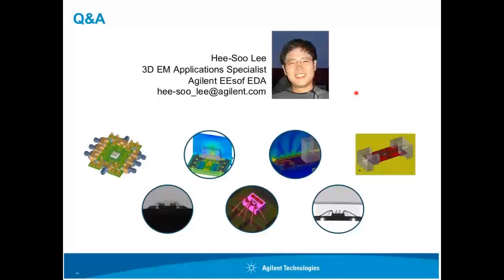There is a very easy way, not only in ADS but also in EMPro. If you go with ADS, there are 3D component structures you can generate, which include the solder bumps. And in EMPro, there is a macro you can use to generate those solder bumps as well. So basically, you just produce those solder bumps, add the remaining structures, and just go for the simulation. That would be the simplest way to do that.